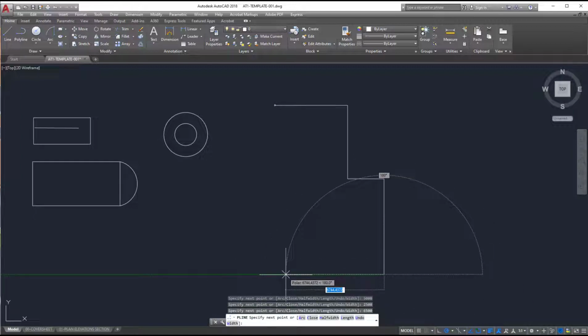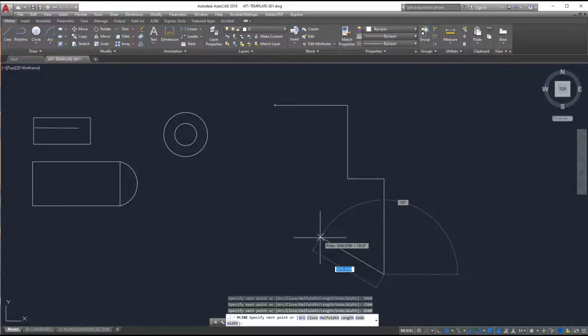And I'm going to use some guides to help me finish this off. So you can see we get these little green dash lines. That's the polar tracking I was talking about earlier in terms of snaps. So it's guiding me to, I think it's every 10-degree or 15-degree interval, to make sure that I'm not drawing off on some weird angle.